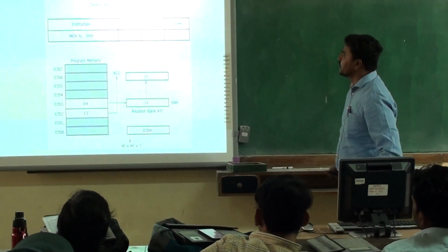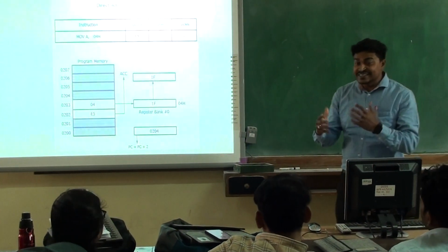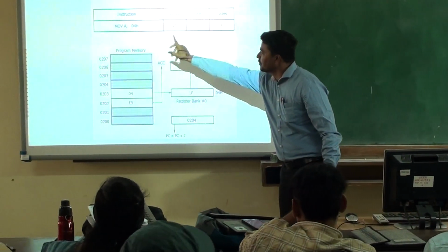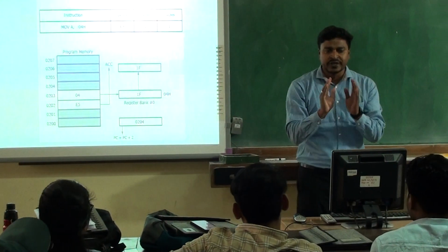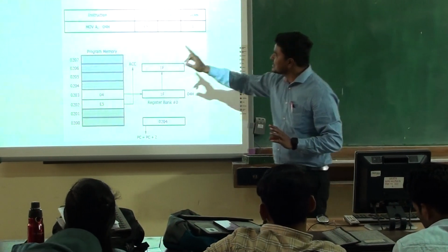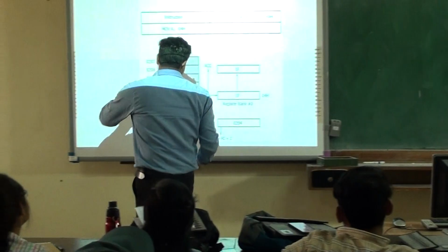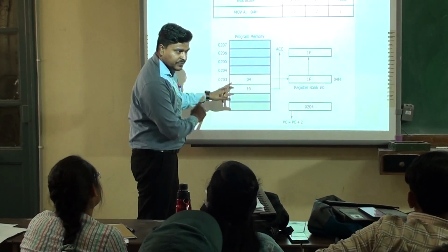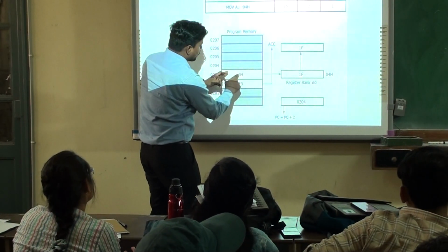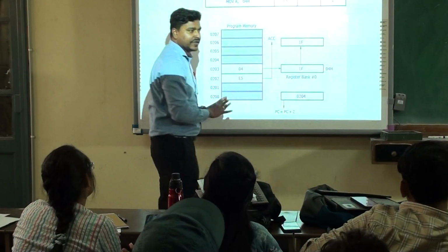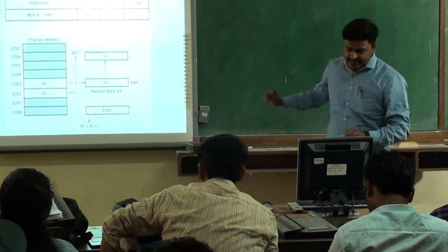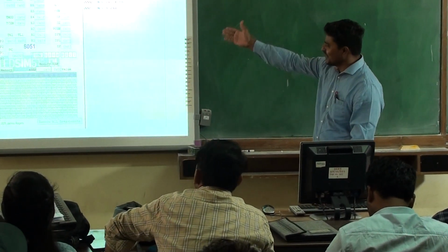This is the direct addressing mode. Now what is changing? The immediate value has been changed. Now we are using a number, 04H, some location in memory, and at that location we are putting some data. When we write this instruction, instead of the data we write the address of the data. Your data is right there at this address. After execution, the data at that address will be transferred to your accumulator. This is the direct addressing mode, and here is also some flavor in the simulator.